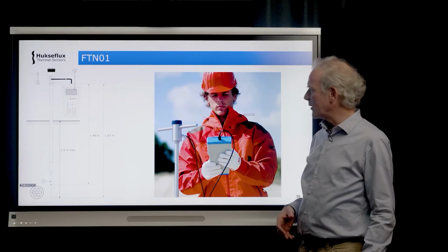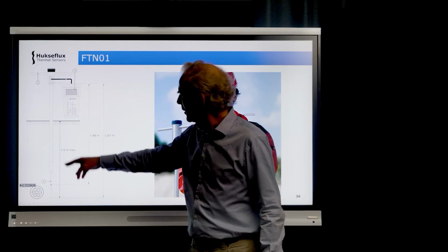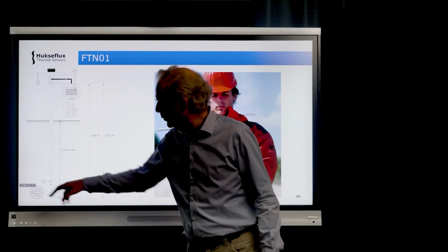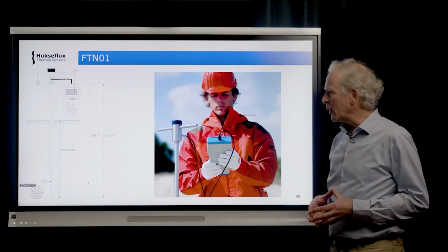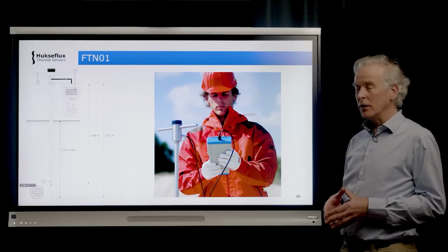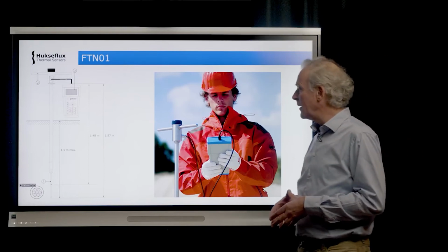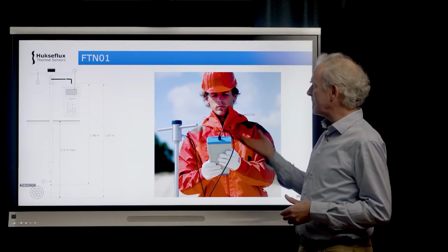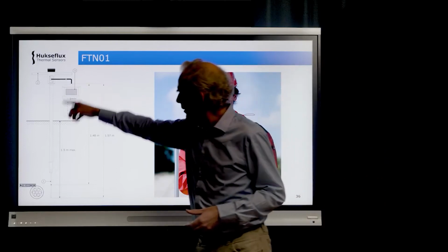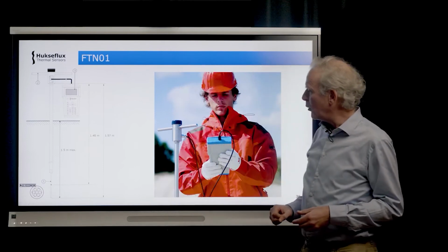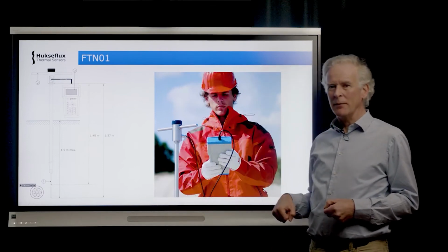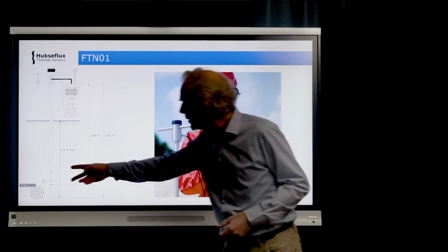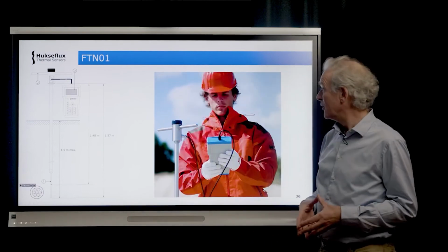So an operator drills a hole to the approximate burial depth of the electrical power cable, and typically that's 1.5 meters below the soil. Then you push the lance, as we call it, in that hole, and the last bit you push the needle in the undisturbed soil.